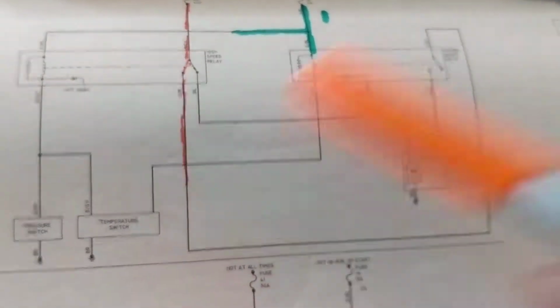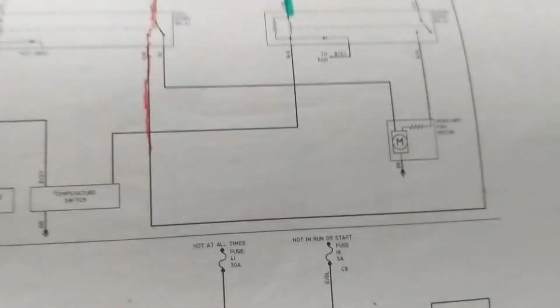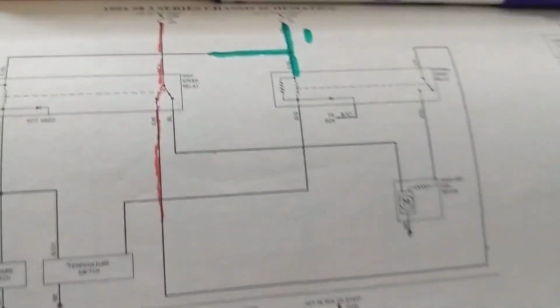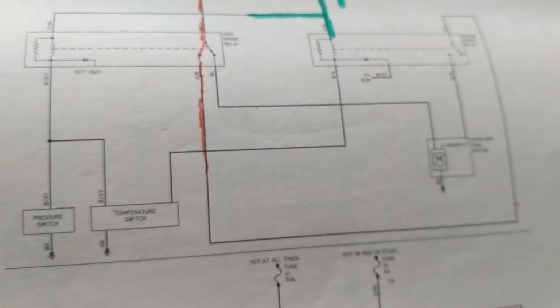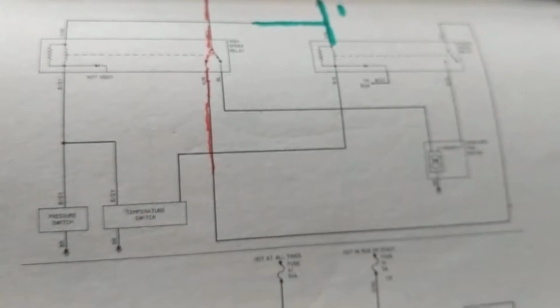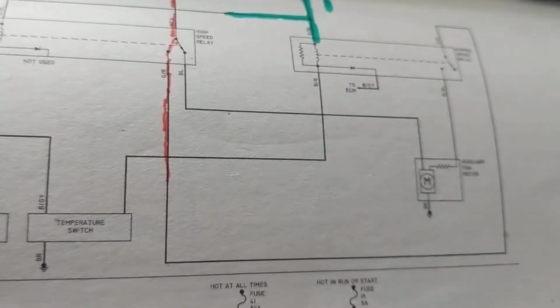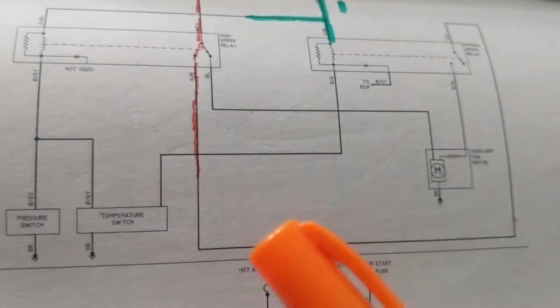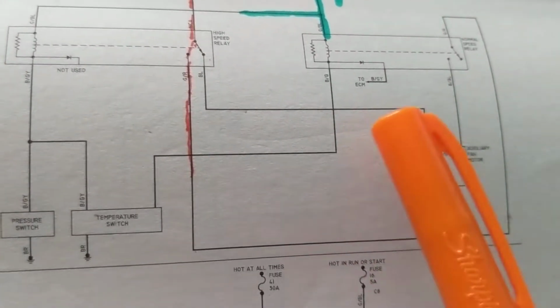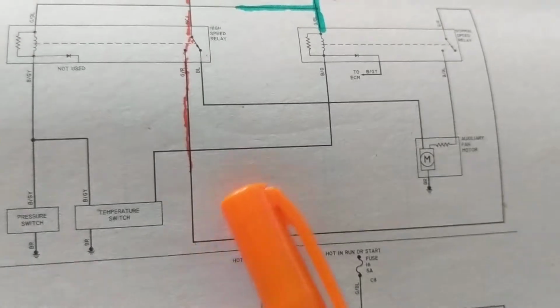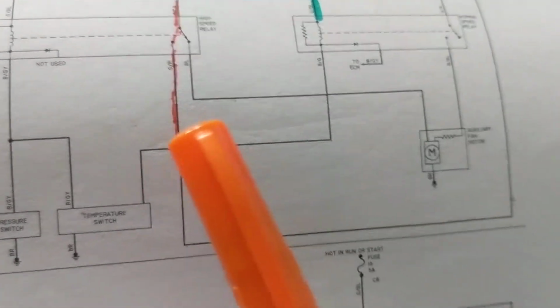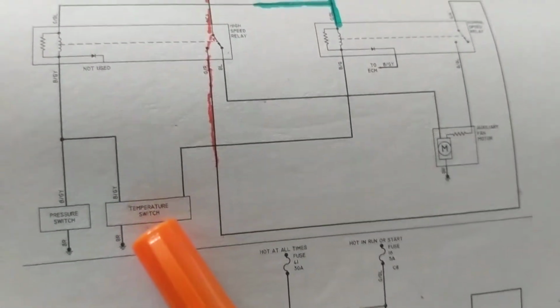If I'm idling, let's say you're waiting for a red light, and that's called idling. Well, of course, on a hot summer day, engine gets hot. Okay? The fans have to go on at high speed. What determines that? The computer looks at the coolant temperature, sees the temperature on your gauge. Sometimes it goes to 190, the midpoint 200, right?